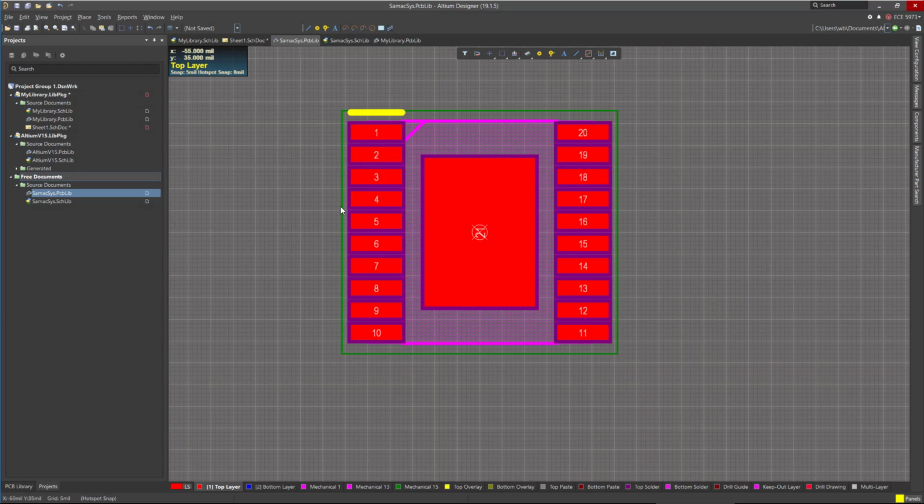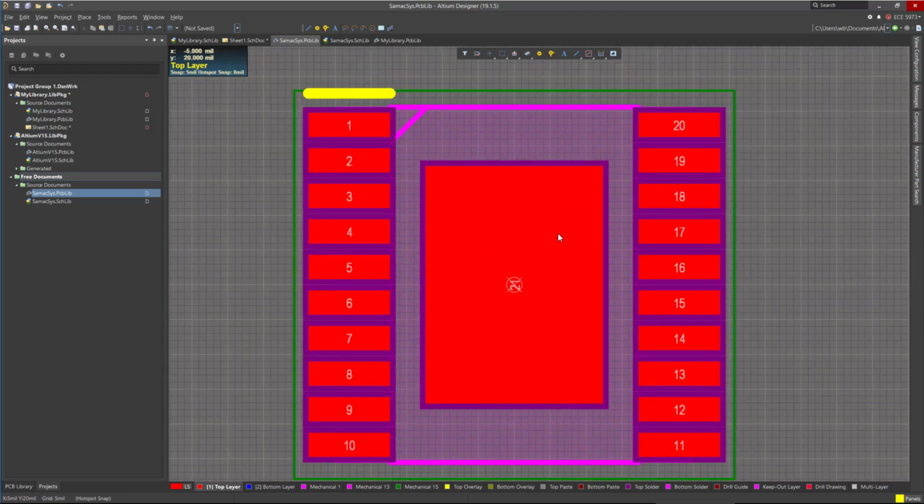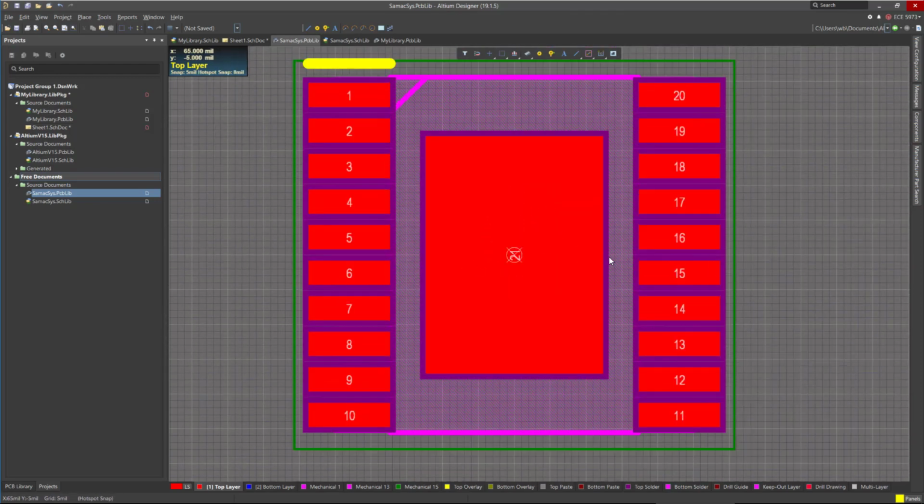Don't just take it and use it as it is without verification or review. This is not safe at all. You might end up redoing PCB fabrication because you will discover that the footprint is not at the right scale. So don't go that route.